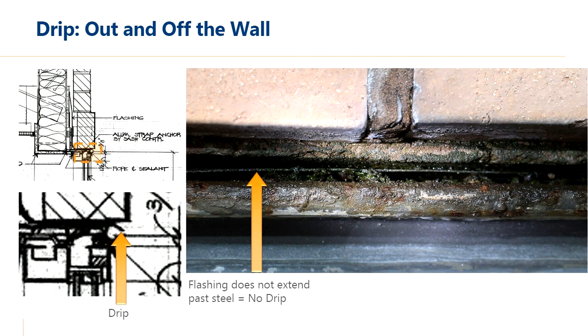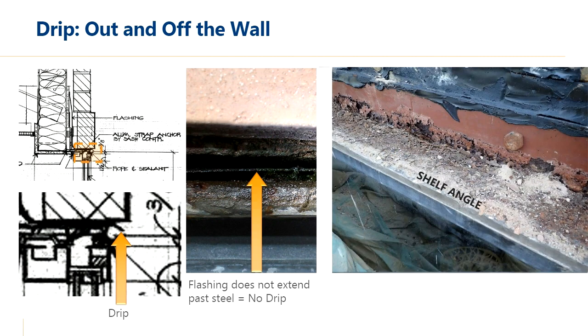You can see the mortar is separated from the steel below, and that's because corrosion is thicker than the original steel, and it was actually lifting the brick, making that separation. So this was a condition of a typical shelf angle that we encountered. Thankfully, even though this doesn't look great, it's really not that much corrosion, and there was a little bit of reserve capacity in the original design, and we did not have to replace any of the shelf angles. So we caught this one early enough to avoid real structural repairs.